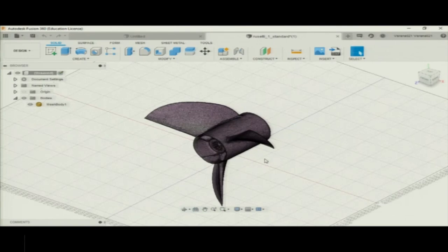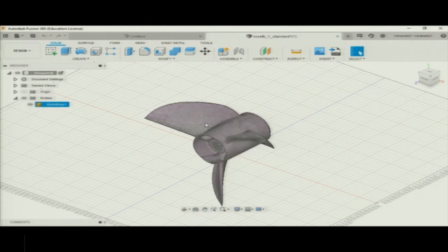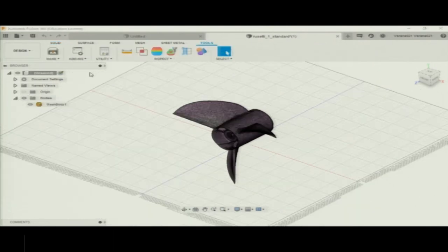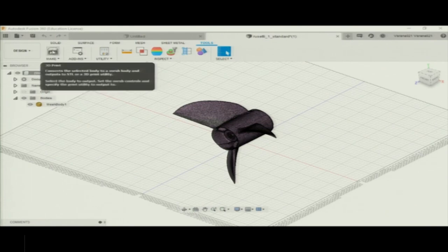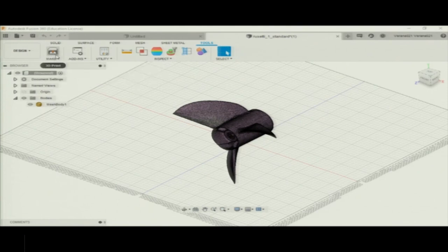And nowadays we have multiple formats like OBJ and 3MF. OBJ is a detailed version, 3MF is more popular. It is a compressed version of OBJ which only provides you the information for 3D printing exclusively. Now, here is an add-on function where we have Meshmixer. Meshmixer is a tool that is used to manipulate and prepare the 3D file for actual 3D printing. So, I am working here in the tools environment.